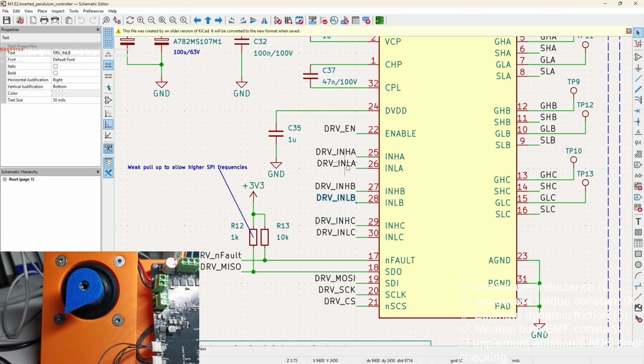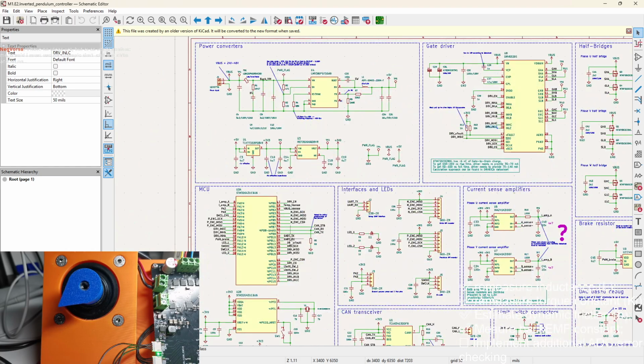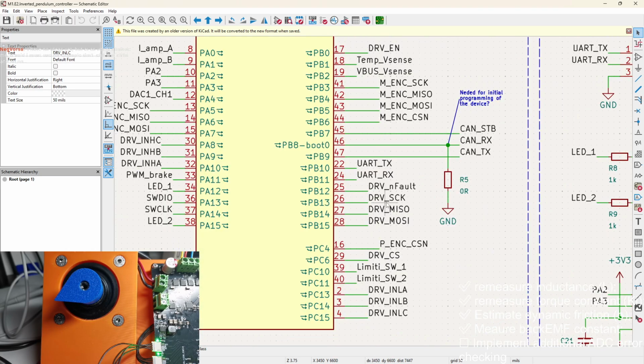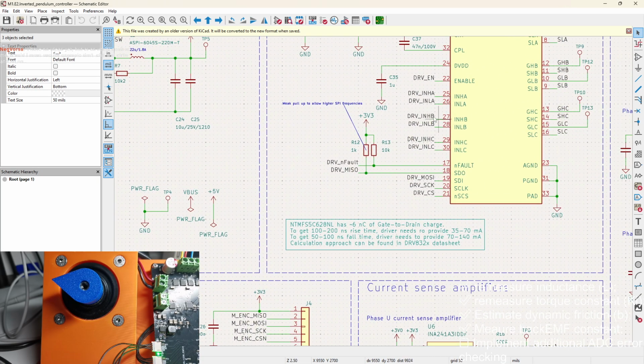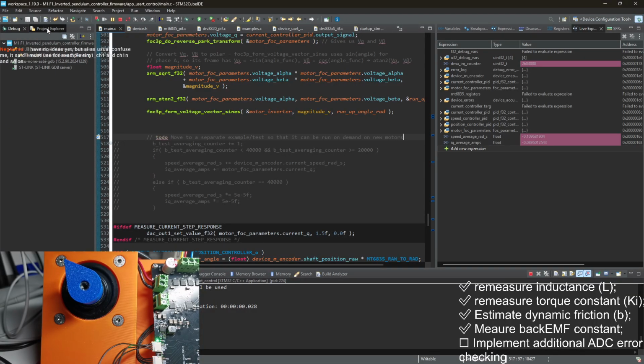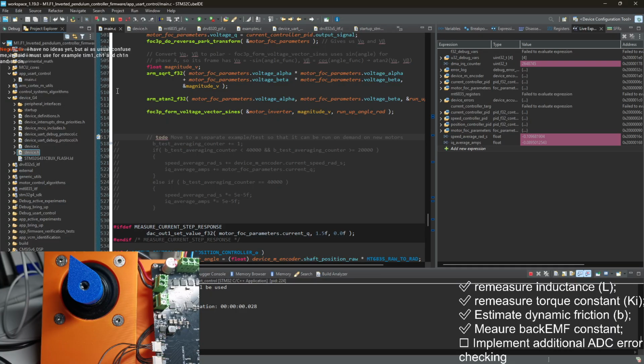And all low ends are just GPIO, any GPIO that I just pull to ground. And you can literally pull them to ground in your schematic design, because in the code I quite literally pull them to ground and never touch them again.